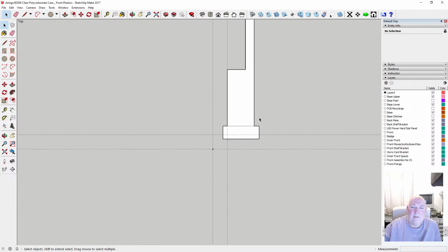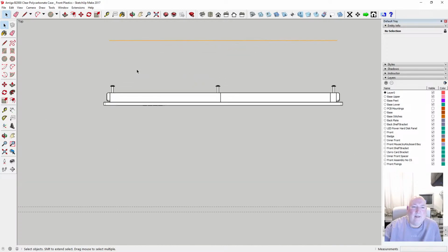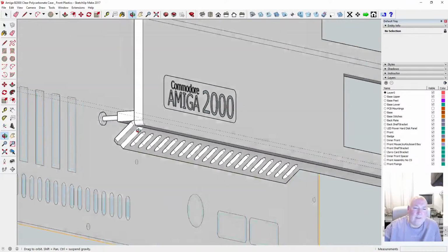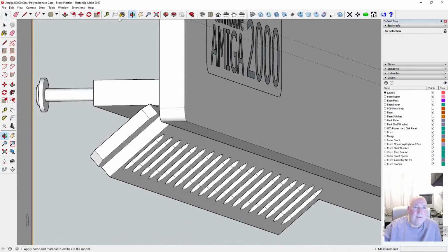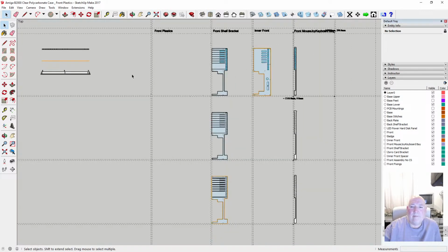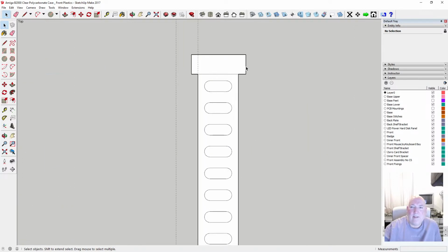Need to find out what the size of the pocket is. So we need to go back to the original here, and I think it was half, wasn't it? Need to see. It's 3mm, so it's the 3mm pocket. That makes it easier because it defaults to being 50% anyway. So here's the pocket. We just got to grab hold of the pocket tool. It's on 45%. We'll put it on 50%.